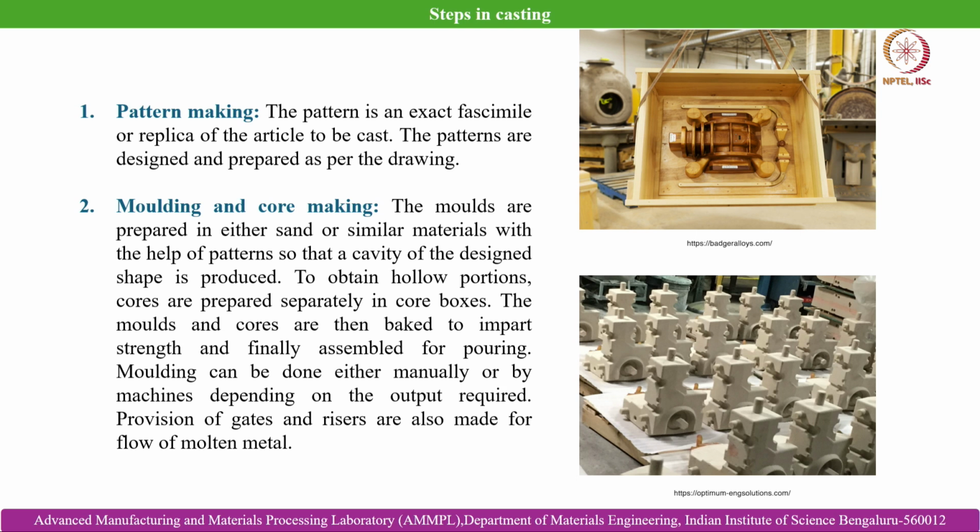That is why it is essential to choose the appropriate mold material for the particular job in hand. If a very high surface finish is in demand, then we can go for metallic molds, and if there are very large components where a significant amount of machining and other allowances are kept, then we can go for sand casting, which will be more economical in that case.